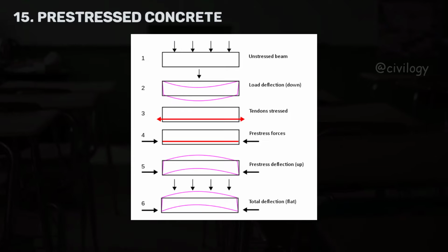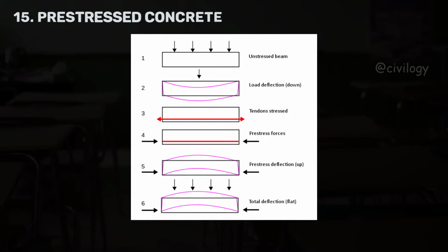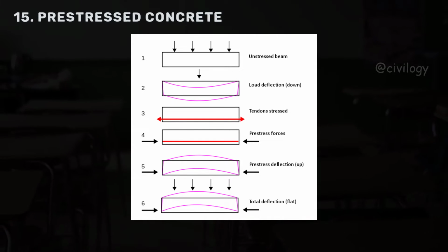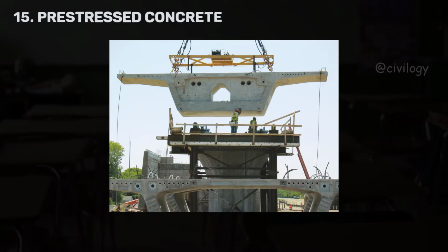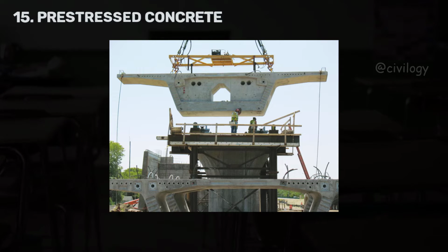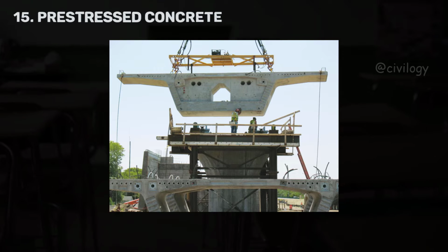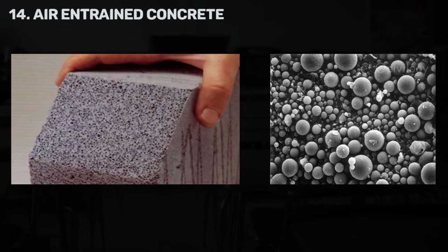This sort of arrangement makes the lower section of the reinforced concrete also stronger against tension. Since pre-stressing involves the use of jacks and tensioning equipment, prestressed concrete is also cast in factories. Prestressed concrete is greatly favored in the construction of bridges, long span roofs, and most structures with a heavy dead load.